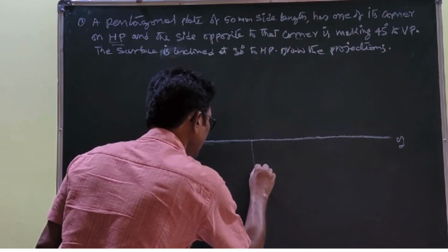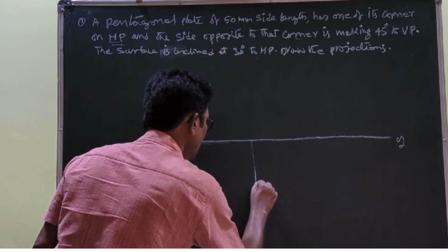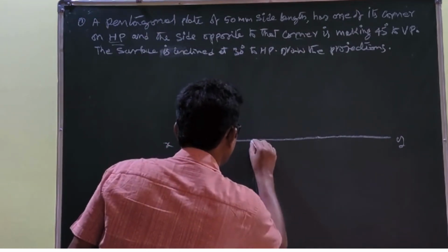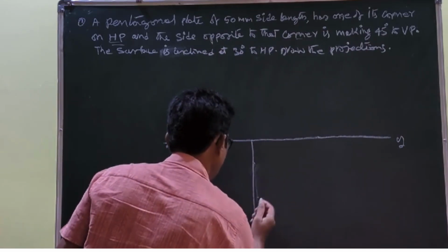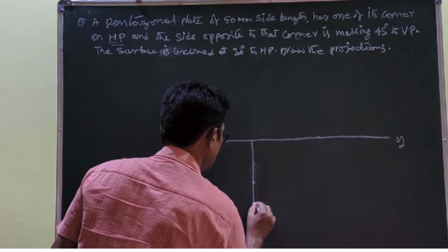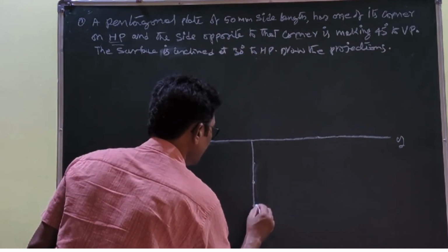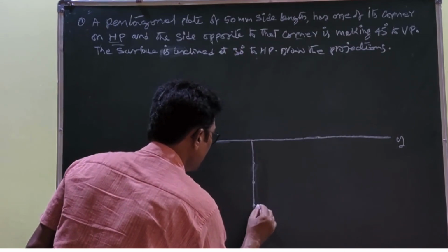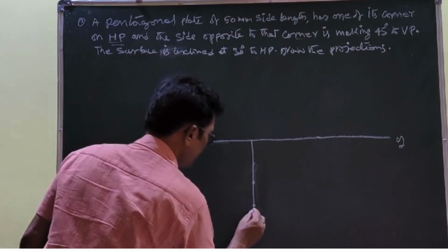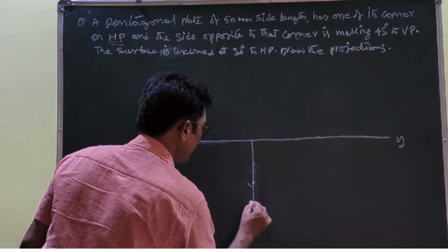Here you set up a length, this is the pentagon side. Let us say that it is 50. First you can construct the pentagon in this position. So next you know that you set up 108 degrees here, you set up 108 degrees here.